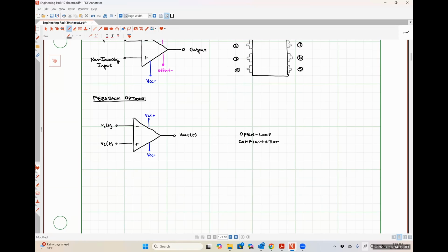This is how we set up what are called comparators for simply measuring signal strength with respect to some reference. So we could use a configuration like this in control systems if we want to set off an alarm if the temperature ever exceeds some specific set point. Okay, so nothing particularly difficult here.